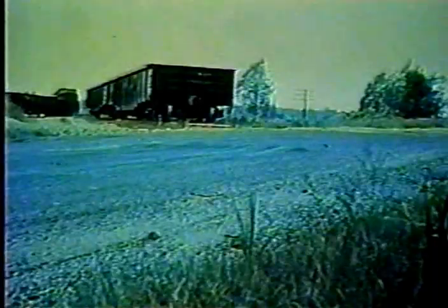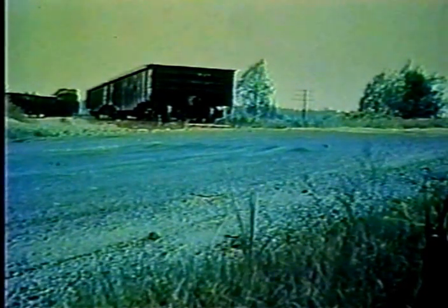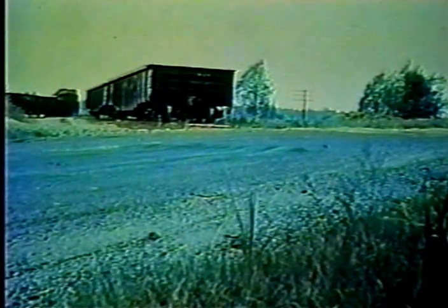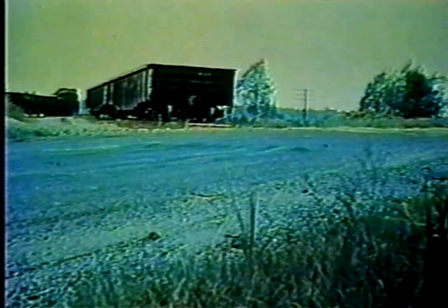Shoving of a pavement can occur, as you see in this particular slide. It happens to be near a railroad siding, so we're looking at large, heavy loads in this area, and it's exposed the pavement to loads that it really can't handle. It has shoved and distorted the pavement, and this is a pavement that would likely have to be totally rebuilt, because shoving and rippling of this extent to me would indicate that you have to rebuild the pavement and provide adequate strength for the loads that it's being exposed to.